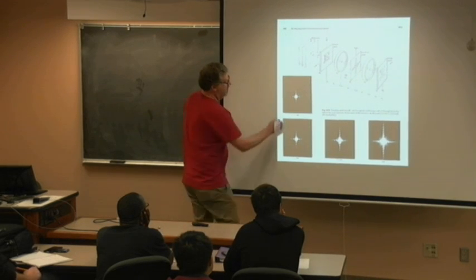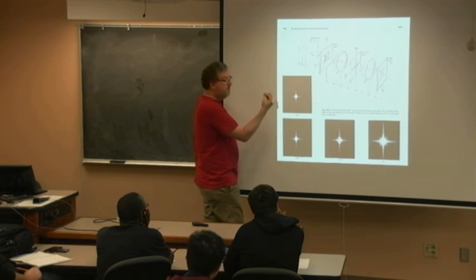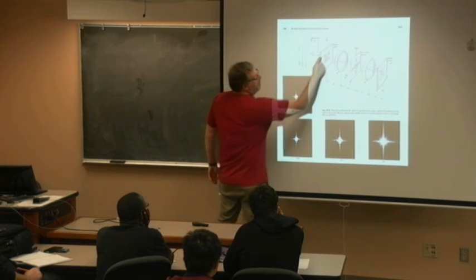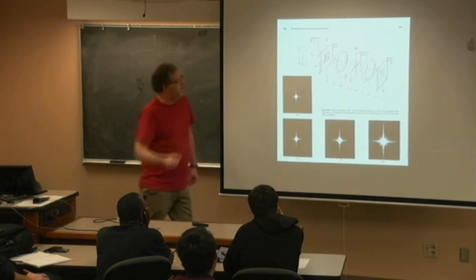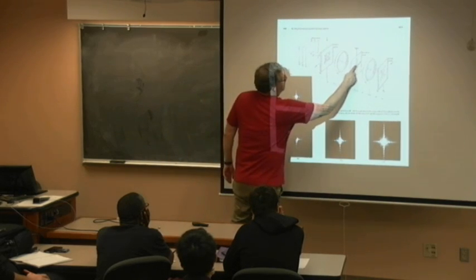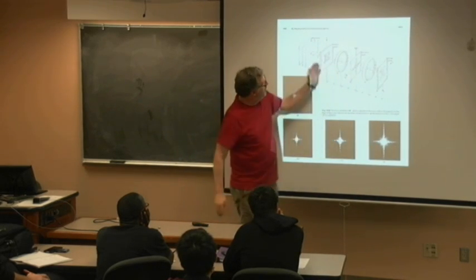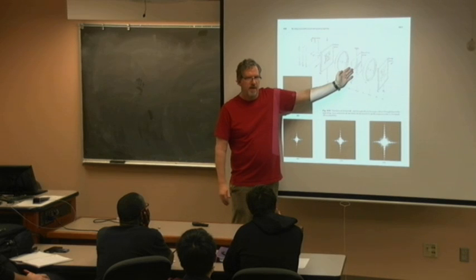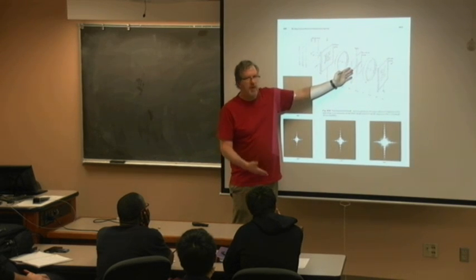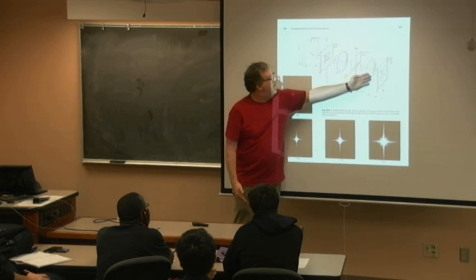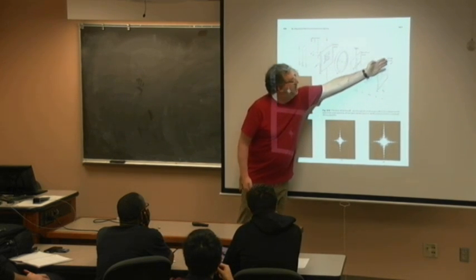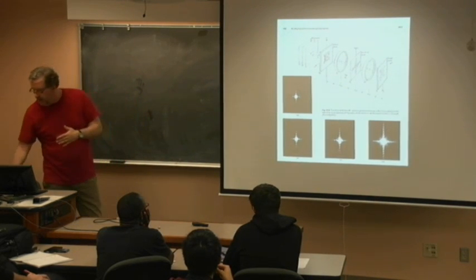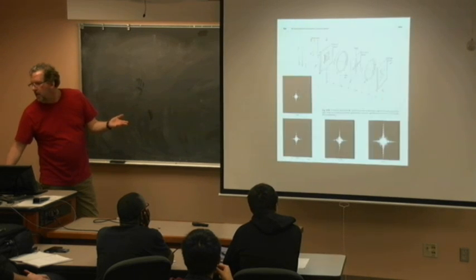Because that's the fundamental that colors it in with the DC color component. And then the outer parts are the higher frequencies, which represent the edge pieces, right? And so if I block that, in this plane I get the Fourier transform, right? And if you take the Fourier transform of a Fourier transform, I get the real image back. So this is the image plane. With that kind of way, I could actually inspect the semiconductors. That's how we do it.